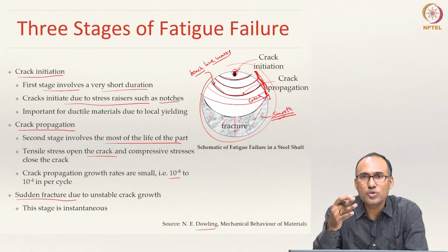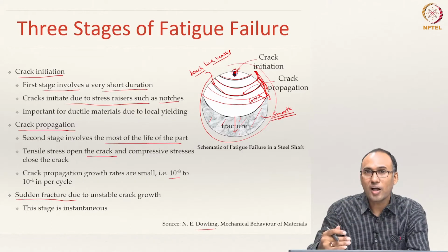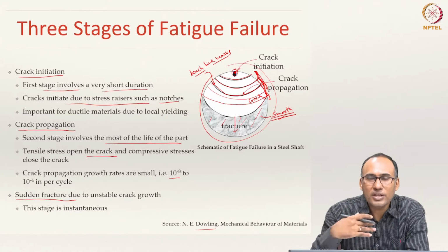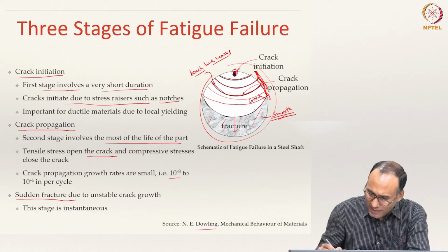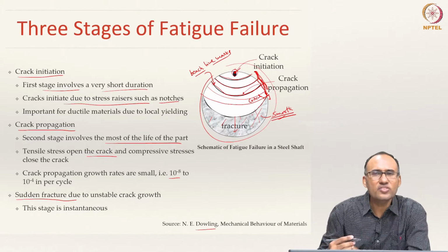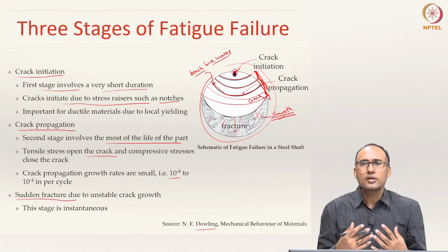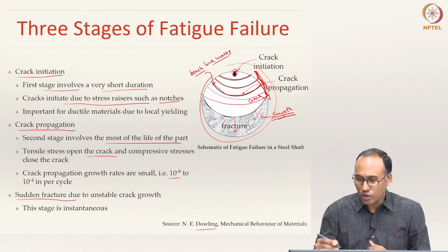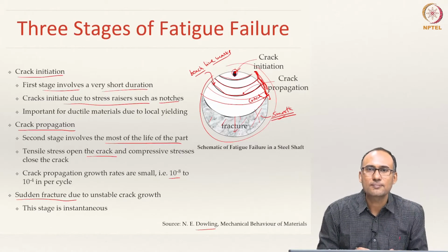That actually gives you an indication that it has failed in fatigue, because all these 3 stages would have passed through before the component completely failed. Okay. So, the final stage is sort of instantaneous. Once the crack becomes a critical crack, it is almost failing instantaneously. That is why you should ensure that you never reach this position when your component is in service.